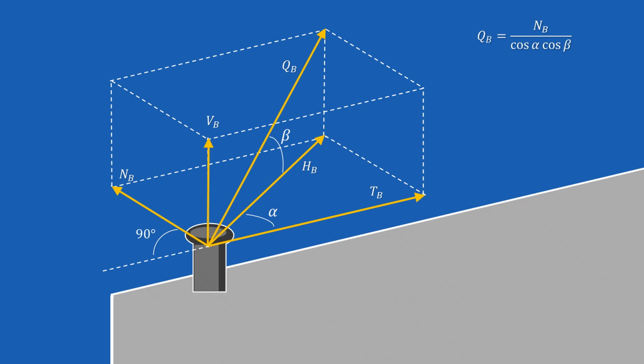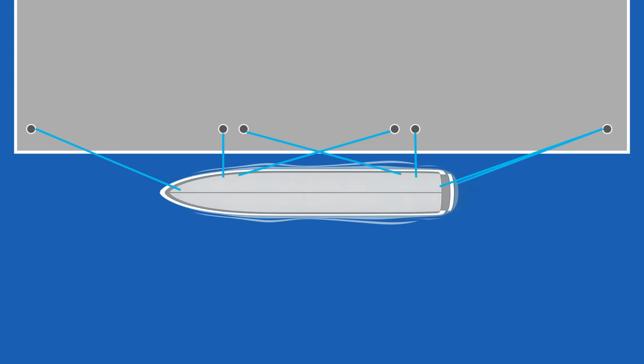be obtained. These vertical force components are particularly important because they affect the global stability and local strength of the dock structure. In practice, not all mooring lines reach their maximum tension at the same time, and many forces partially cancel each other out. This is why design guidelines provide recommended mooring loads per bollard, especially useful during preliminary design stages. Bollards located at the ends of a berth are usually designed for higher loads than intermediate bollards due to